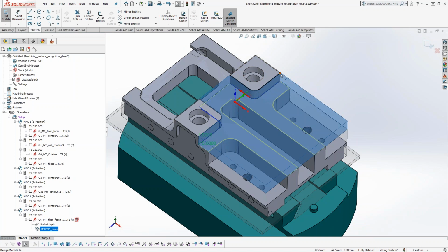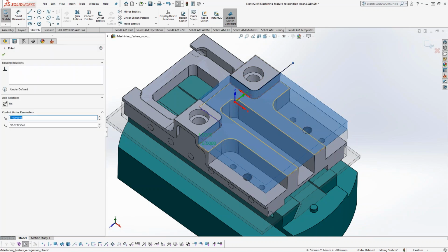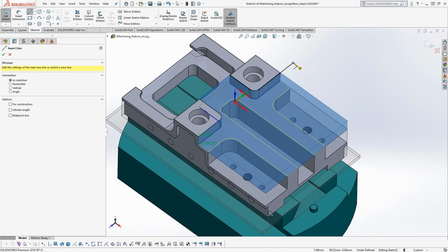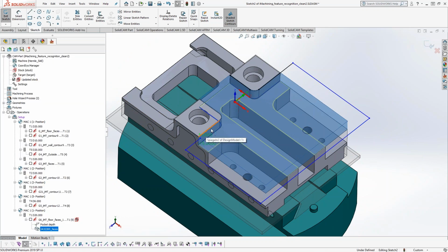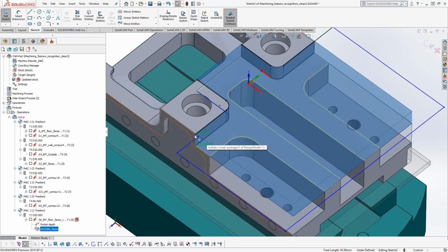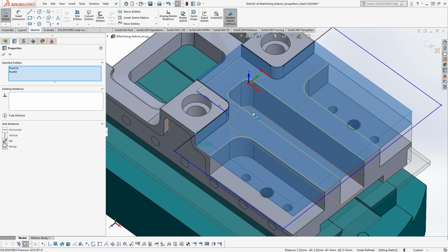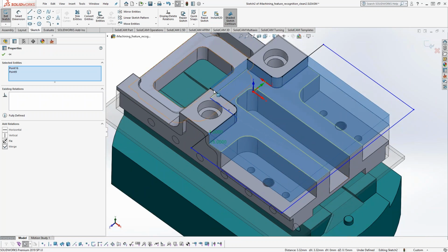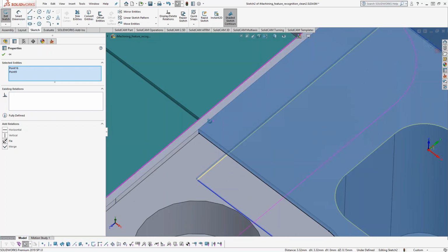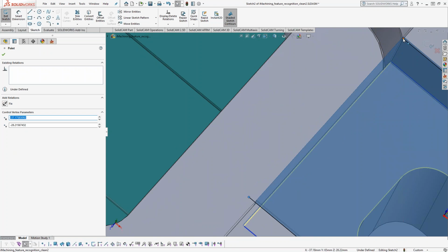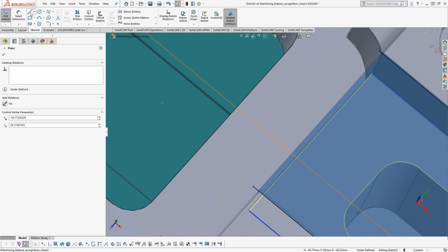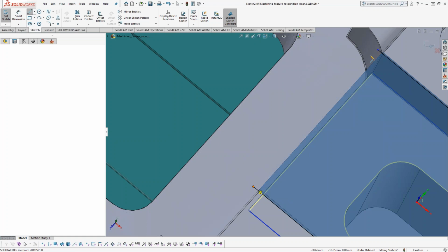You'd want to take the lines of the stock, convert them, drag this out, and then I would be manually defining some sketch that said, even though I'm machining this feature here, I know that because of the way the stock is, I need to do all this sketching. And let's be honest, even over here, we have a little bit of material. This is the type of stuff that we as programmers have to do.